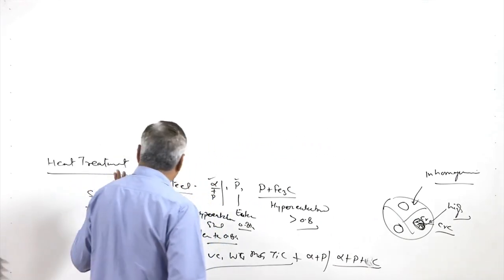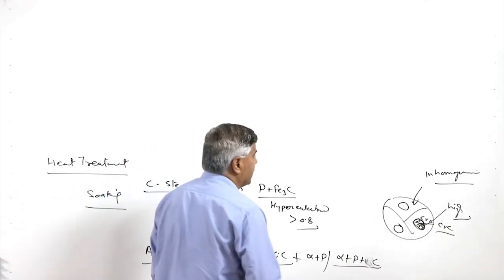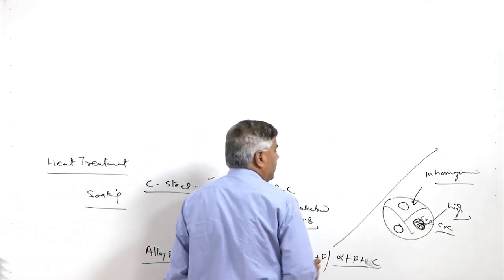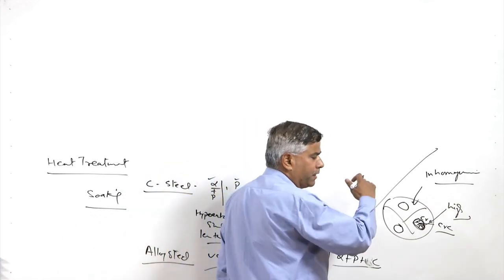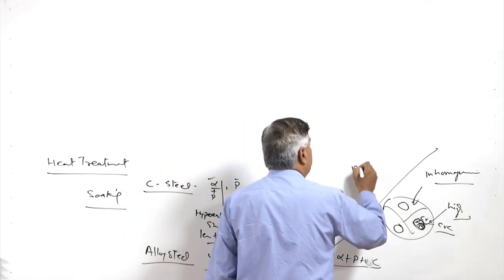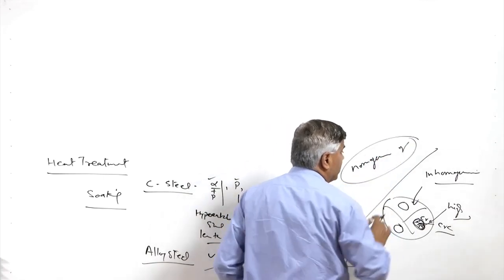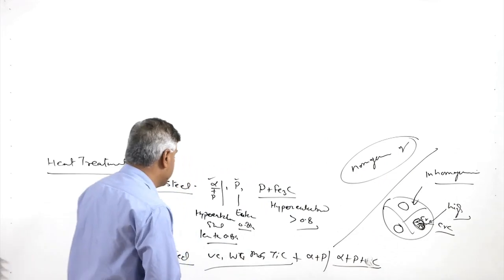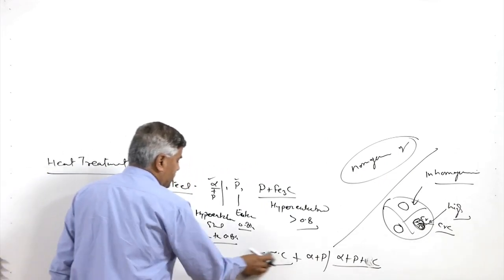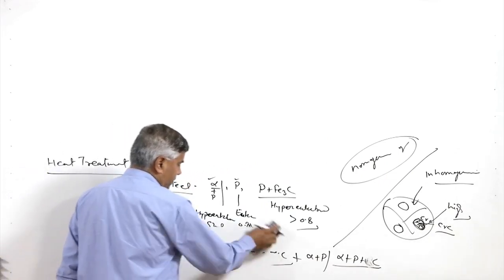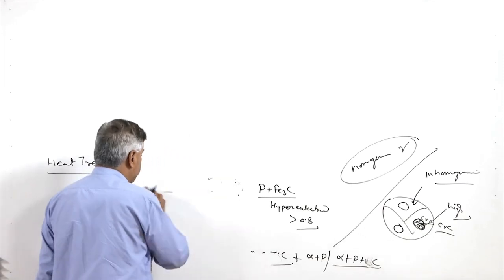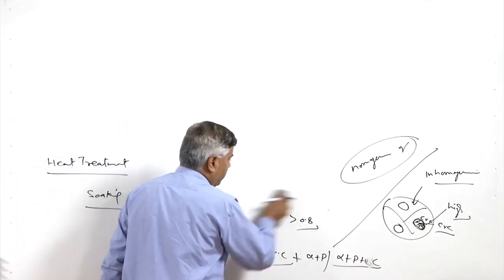So, in steels it is important that after the heating, meaning heating at a particular temperature and then soaking, homogeneous austenite is produced in order to have the desired effect on the transformation, so that the desired phases can be achieved for the heat treatment purpose.